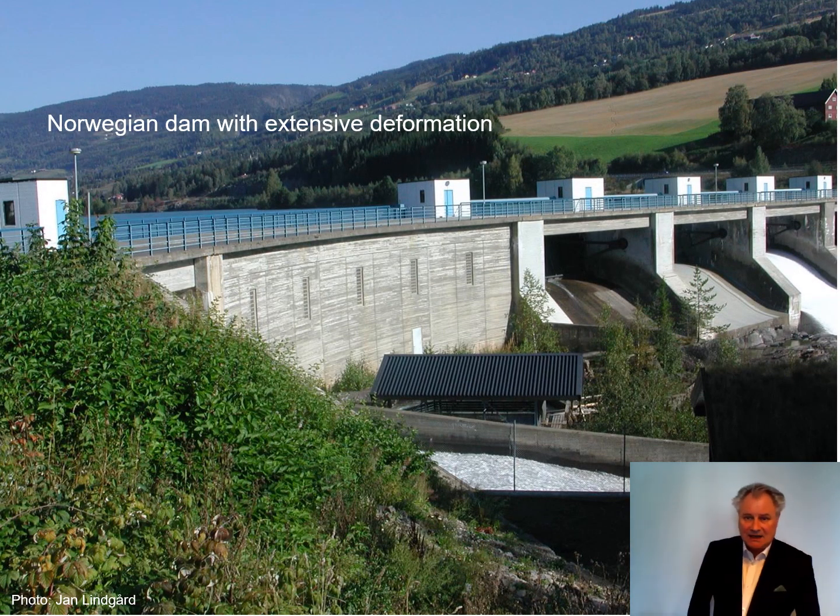Here is a Norwegian dam called Hundefossen. They realized in that dam that they started to get some problems of opening and closing the gates. As you can see to the right in the picture, there's some gates where you're opening and closing for the water to go through there. But they had some problems of opening and closing the gates, so it was obviously that the whole structure was deforming and expanding.